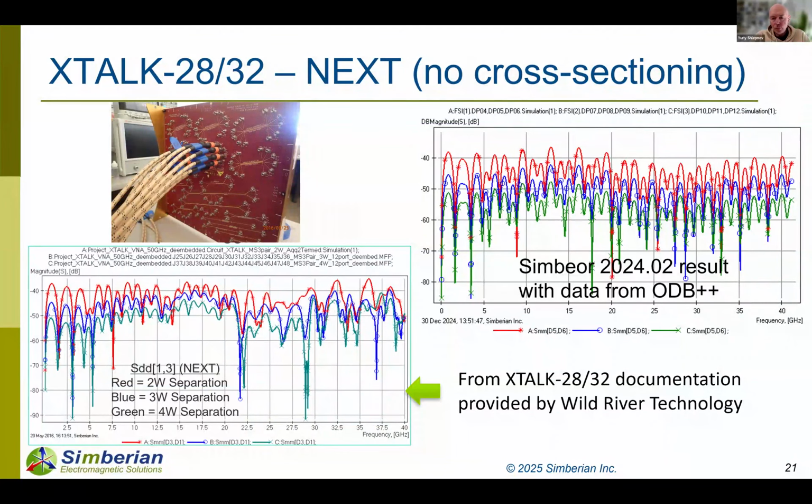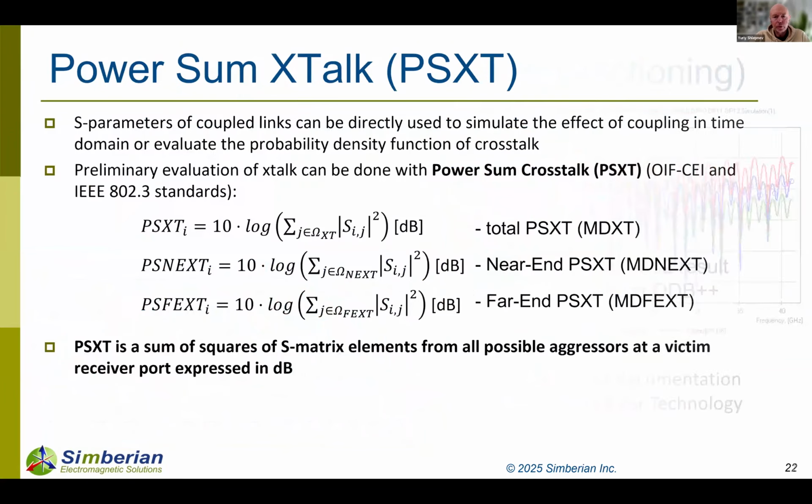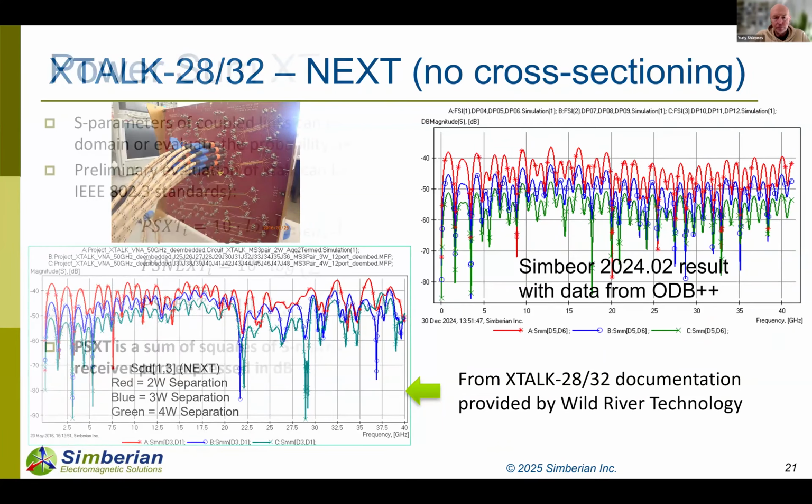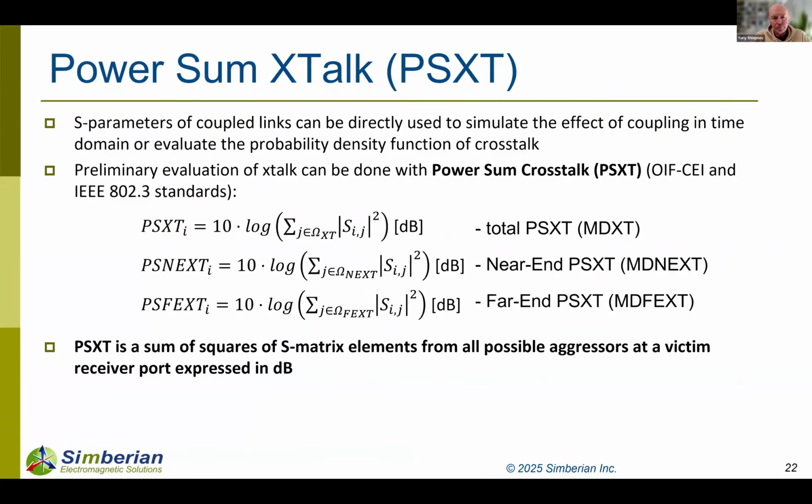This is the most obvious thing to evaluate the crosstalk. In the form of S parameters, the smaller the value in dB, the smaller the value in volts is going to be. How it correlates with this, we'll see. Additional steps are needed. Right here I show only the magnitude of scattering parameters. There are also phase, delays, and so on, that define the behavior of the signal in time domain.